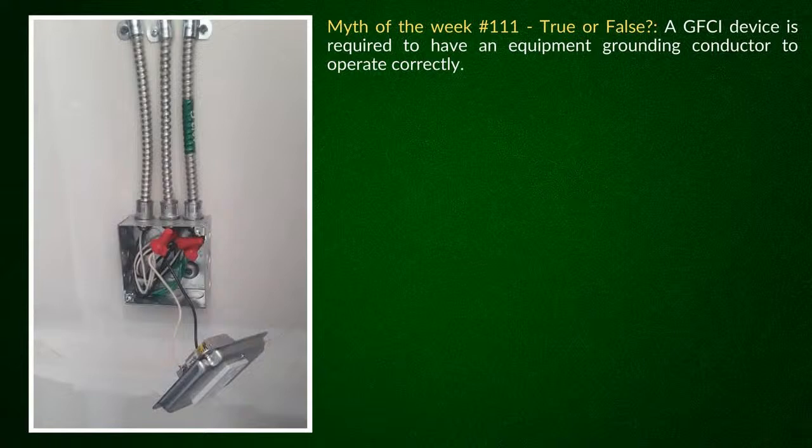on an ungrounded circuit, where you have ungrounded receptacles. And then what you do is you label that "no equipment ground," and then when you test that circuit, you have to use the test button. A lot of the inspectors think you could use your test button on your tester, but you actually can't, because it's not going to work, because that completes the circuit, that tests the circuit between the hot and the ground. So that actually doesn't work in that case.